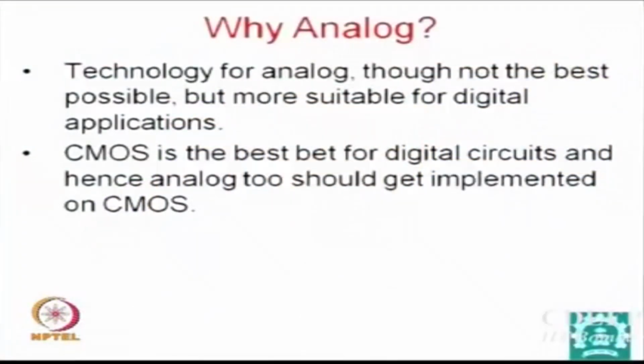Now, the major worry for analog designers is this. Independent analog chips are in very little demand. Op-amps are made and they are sold, but only instrumentation people buy them. Very few other systems buy op-amps per se independently. So I can design the best op-amp, like an 8576, a very low noise op-amp, and I can sell that on a board as a single chip. But in a total mixed-signal system, 80% of the part on that chip is digital, or maybe more at times.